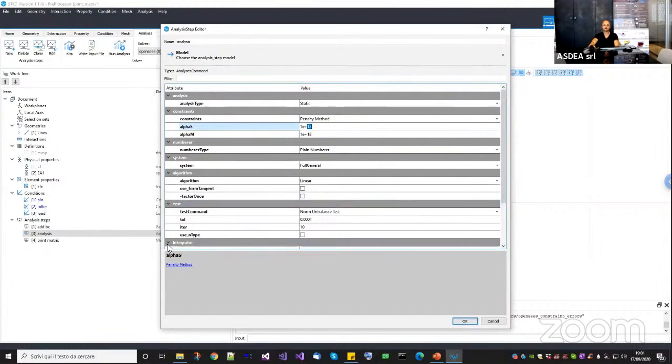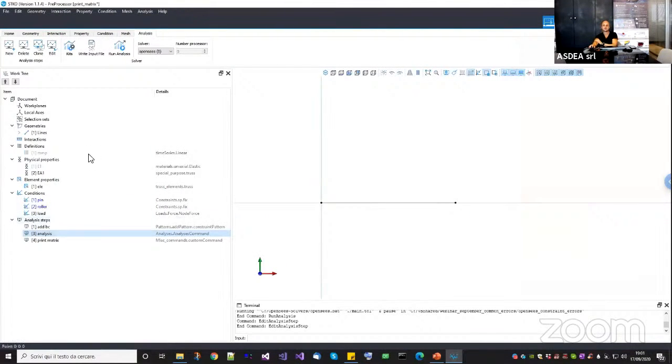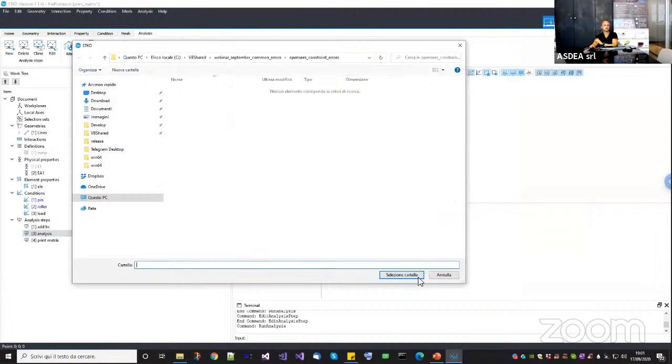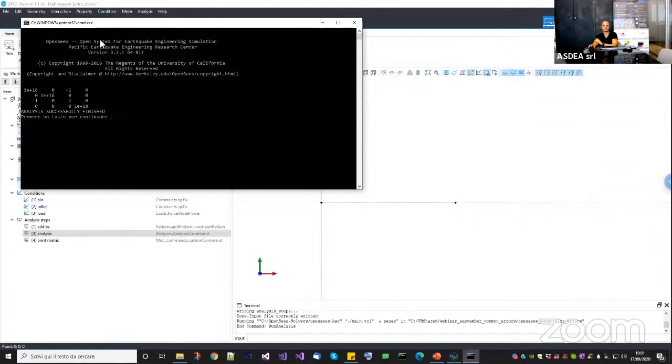Now there is a simple rule to follow. You need to understand what is the highest stiffness component in your matrix. Now in my case, it will be 1, and this value here should be the order of magnitude of that, which is 1 plus 8. So in this case, I should have chosen 1 to the power of 9, okay? But in this case, it is not important. I just want to use this high number so that you can see it in the printed matrix.